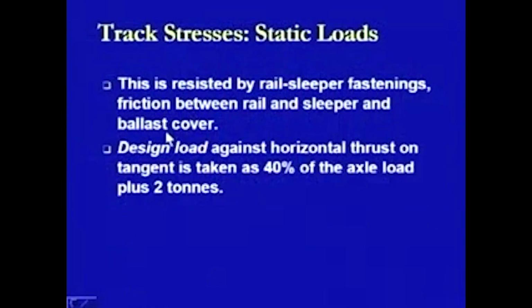The similar is the condition for the ballast cover. Because of these movements, because of the lateral movements, the ballast cover becomes a little loosened out, and this is another important thing because the ballast is being provided so as to provide the lateral strength or stability to the track. And if this is losing out, then in that sense the total lateral strength or stability of the track will reduce.